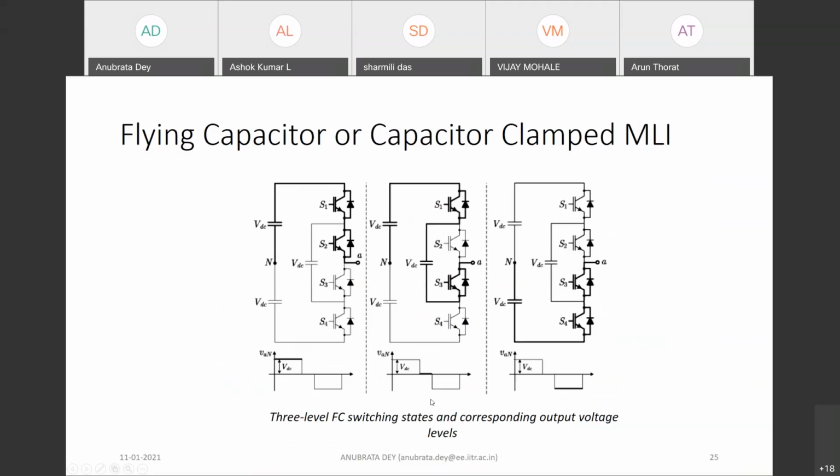But when you want to get this middle voltage level, you have two choices. One choice is shown here, the other choice is not shown in this particular figure, but you have to understand the other choice would be that the other two switches, S2 and S4, are on, and the bold path is shown. That means these two switches are on. When these two switches are on, as shown in this figure, and assuming the pole current direction is outward,